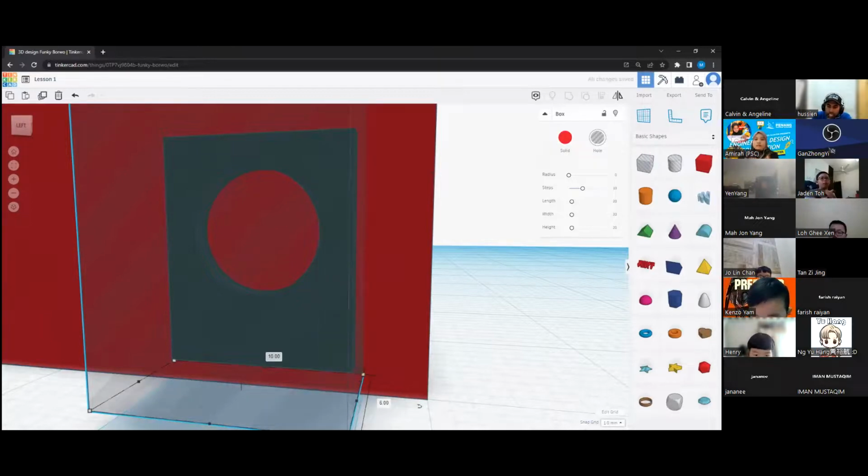That is because of the snap grid here. So if we want, we can change it to 0.5 mm. We can try that first. So if we adjust it now, you can see it is almost covering the space. But if you want it better, you can go to 0.1 mm. This is much more precise, basically. So we can use that.